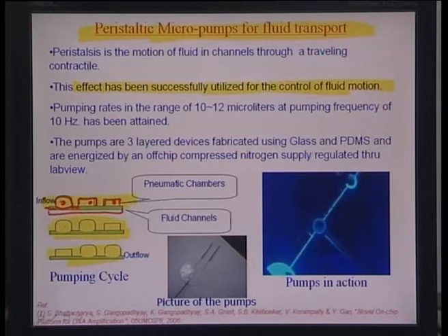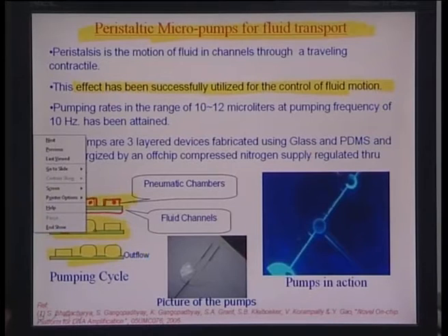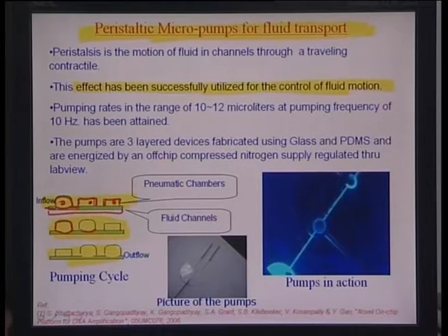and then after this forward momentum is gathered, you keep this closed so that the fluid cannot rush back, and close on the second. So you start compressing the channel on the second. So here the fluid cannot rush back, this path is closed, and the only forward direction momentum would be implied onto the fluid channel. Mind you, this green layer here indicates the fluid channel, and there is a layer on the bottom here which is the base or the glass substrate, and then you can have valve 2 and 3 operated, and the sequence can keep on rotating so that the flow picks up from here and goes all the way up to the outflow.